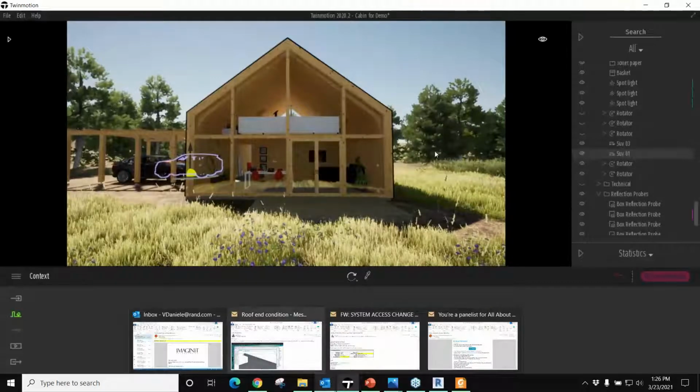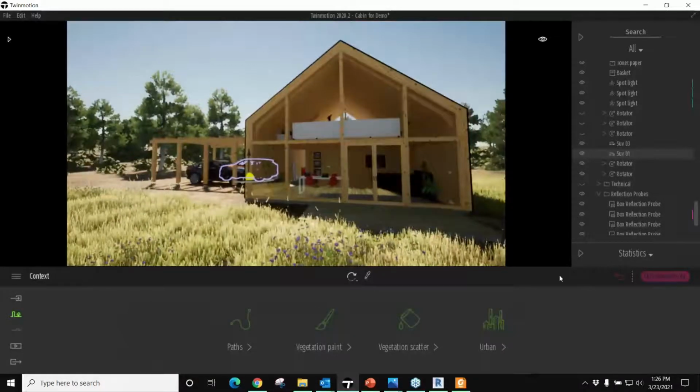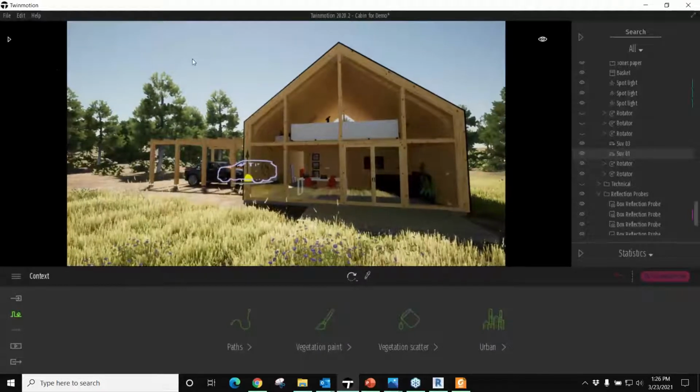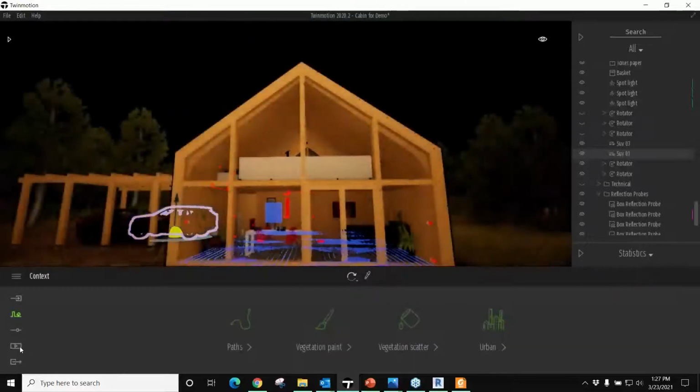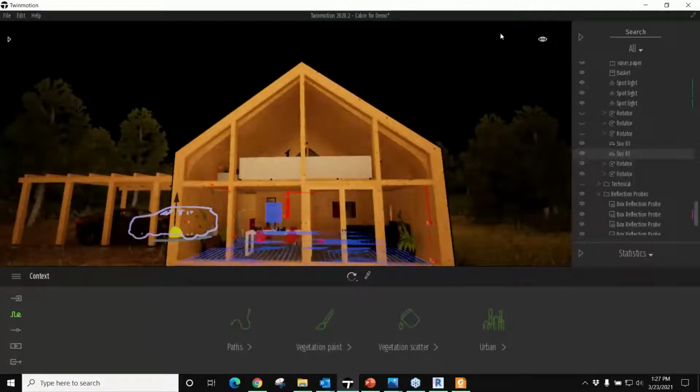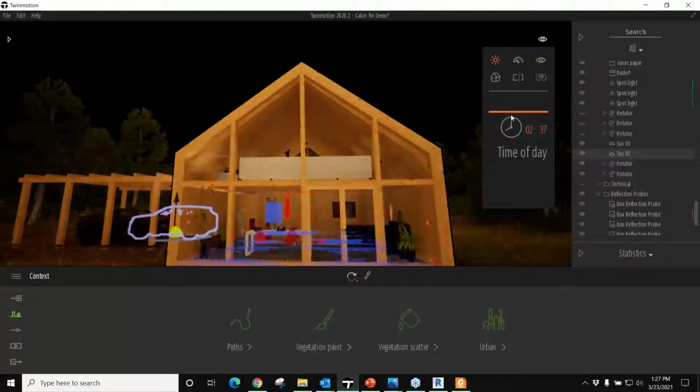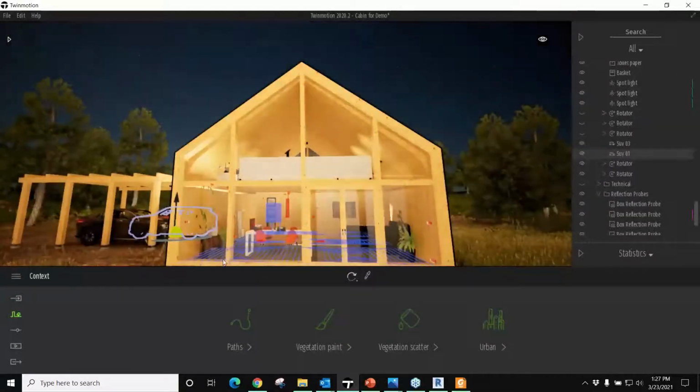All right. Now just quickly, let's see, we've got 15-ish minutes. So with the lighting inside of Twinmotion, if we look up in the sky, it's a clear sky. We do have the option to change the day lighting in Twinmotion. We can make it go from daytime to nighttime. We can affect the weather, and all of that is really done through our context settings.